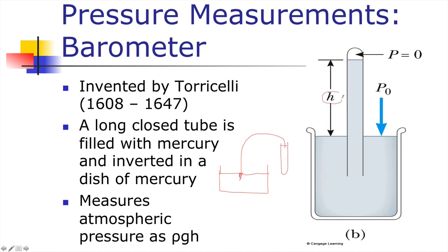Then this rise in height is the same as pressure, because according to the definition that we saw, pressure only depends on height. That means if points are at the same level, the pressure due to the atmosphere at this level and the pressure here because of the height of the mercury are the same, because the depth where you are dictates how much pressure you experience.